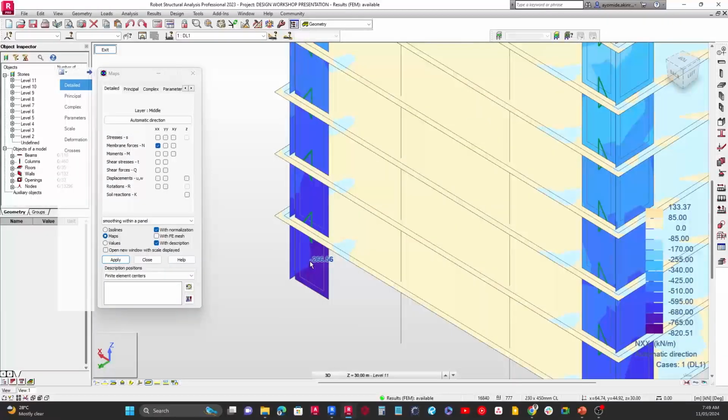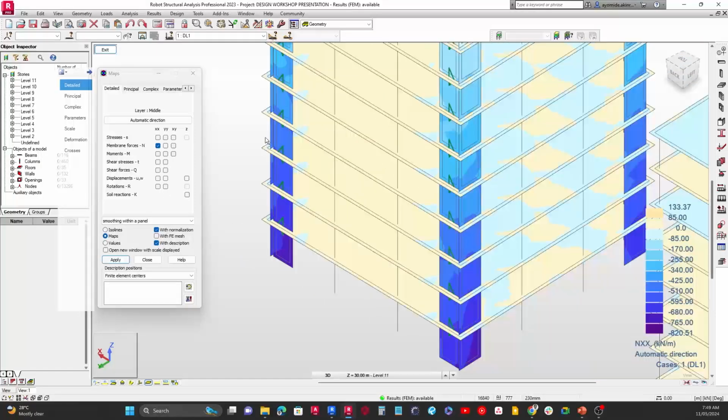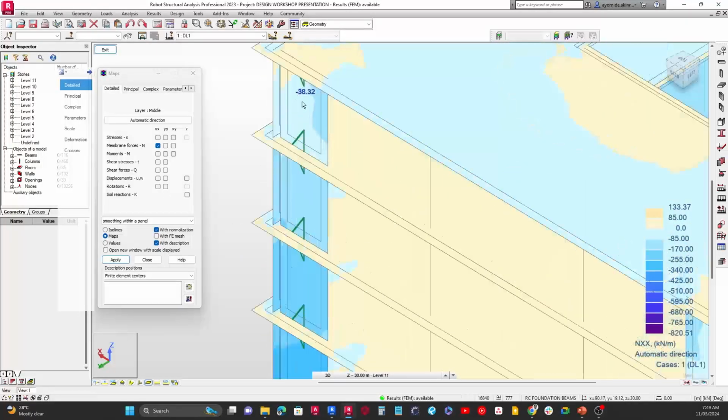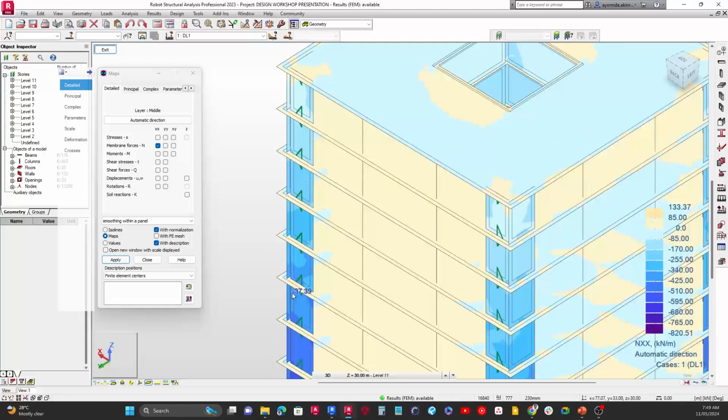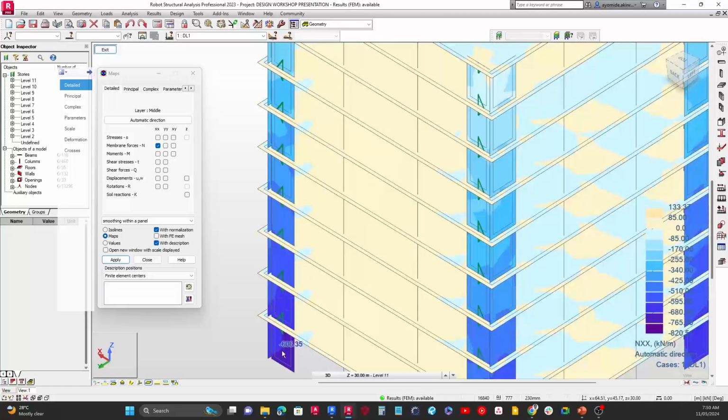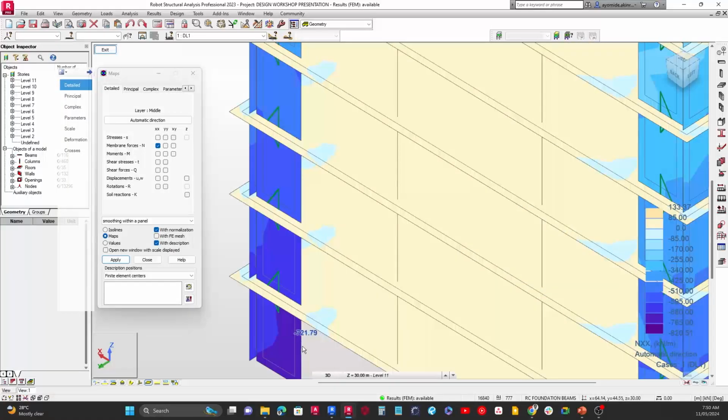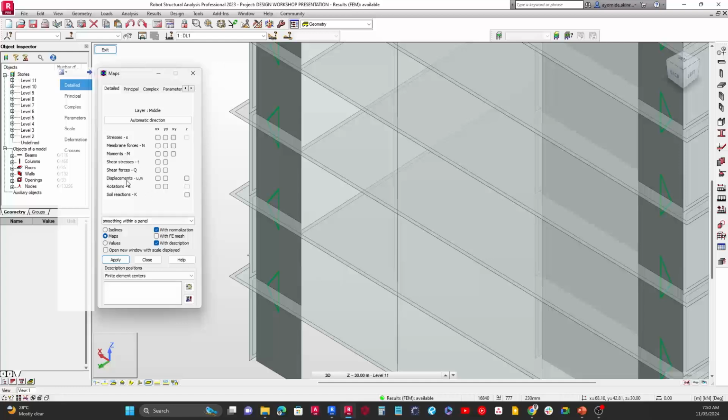to this point here. Meaning that the same thing that also applies to columns applies to walls as well, right? In terms of section. So what that means is that if a wall, for instance, has a width of, let's say, 200 mm at the top, due to the amount of loads that it's carrying, at the bottom, for instance, you notice when they are stacking walls, at the bottom here, we can have something like about 400 mm thickness, maybe 600 mm thickness, you understand, just because of the loads it's carrying. Also, the same thing also applies to columns as well. Okay, all right, let me turn this off.